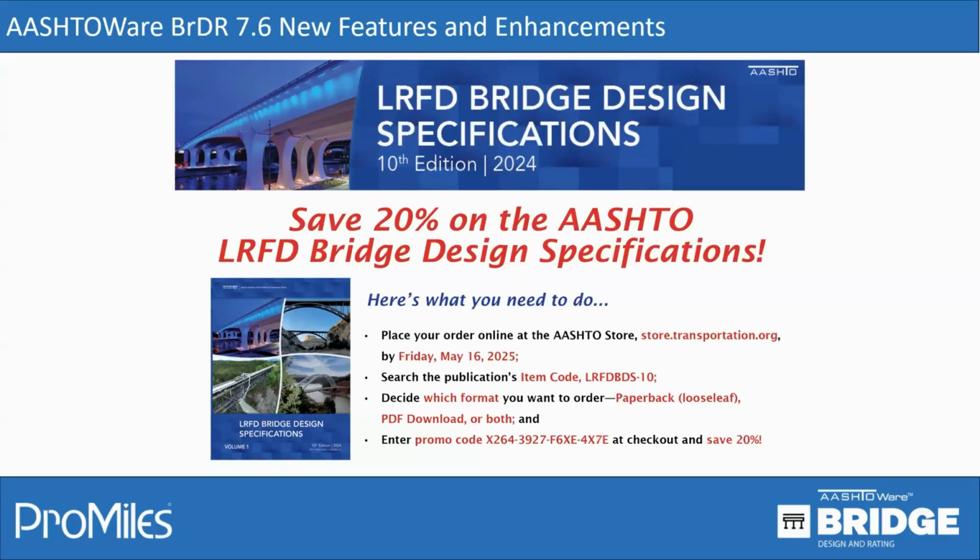Next question. I'm not entirely sure which section this was for, but how are these changes going to be implemented in the rating portion of BRR? I think I can answer that. In general, if there is a design portion of the code that would compute the capacity using the LRFD spec, then that will still be using the LRFD spec with the new spec updates. So essentially the latest MBE in version 7.6 will be using the latest LRFD spec from the 10th edition.